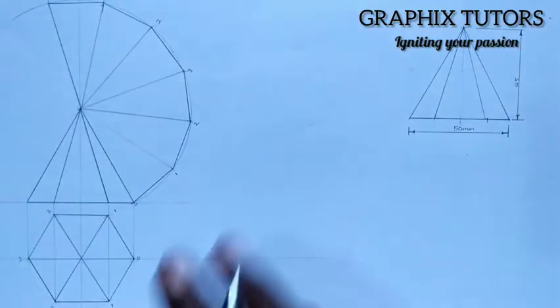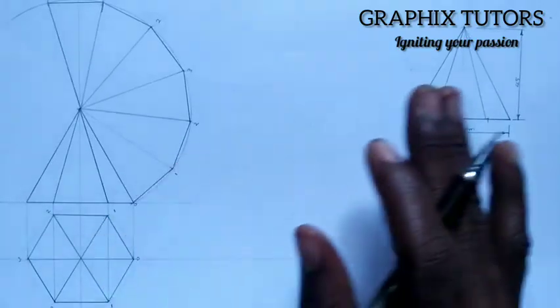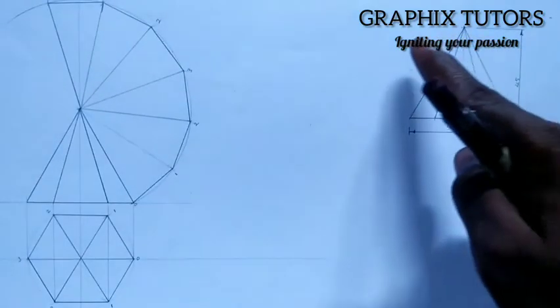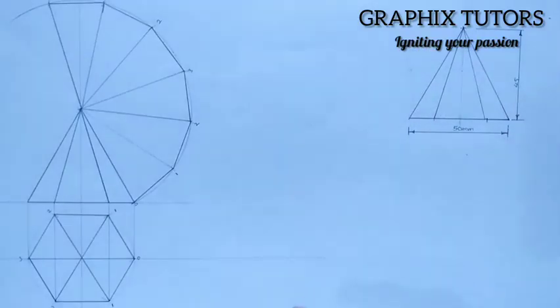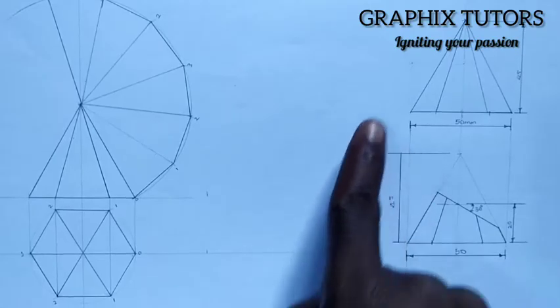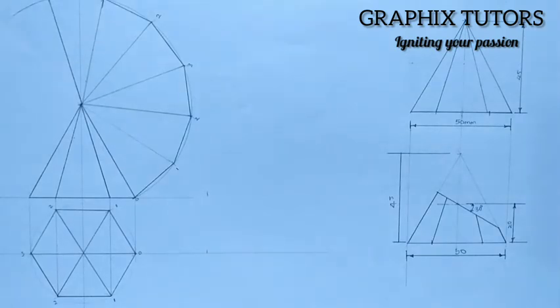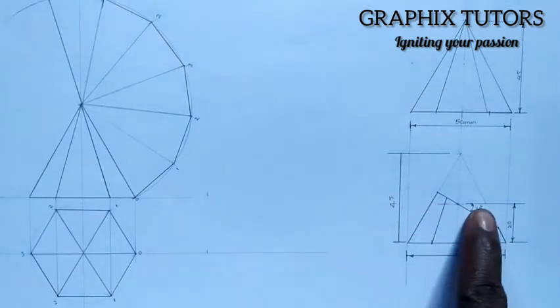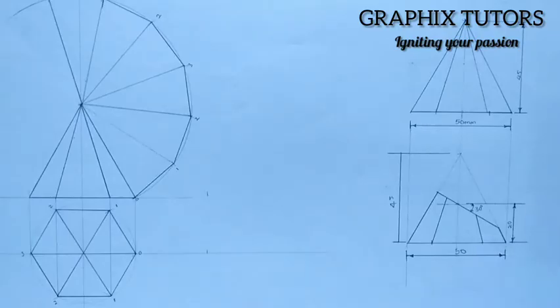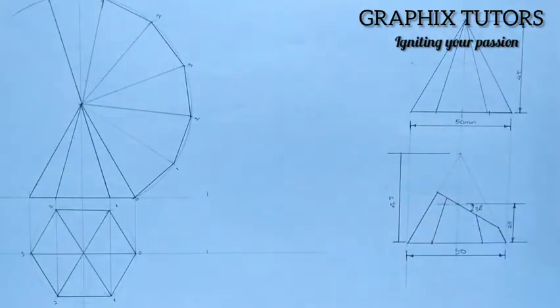Now, this is case 1. Let us look at case 2, which will be the modification of this. Let's see what happens if we cut this at an edge here. Now, you look, we have cut this pyramid at an angle of 30 degrees. The angle can change, it might be 45 or any other angle. We have cut it at an angle of 30 degrees at a height of what? 20.